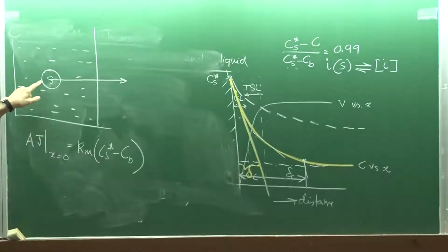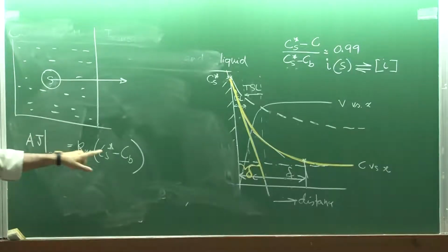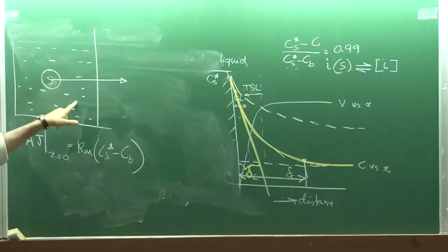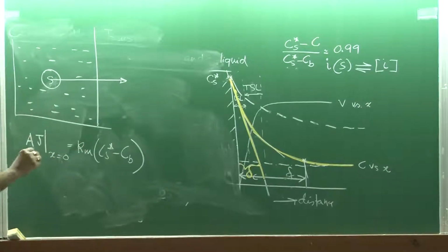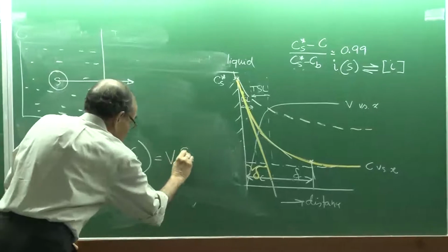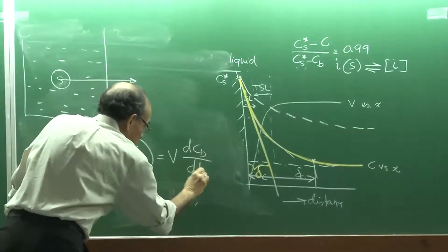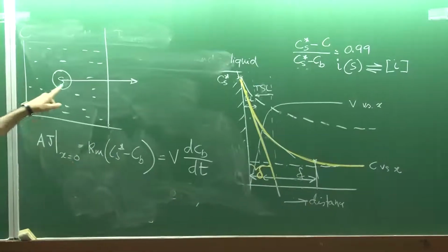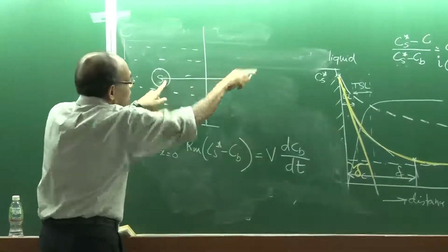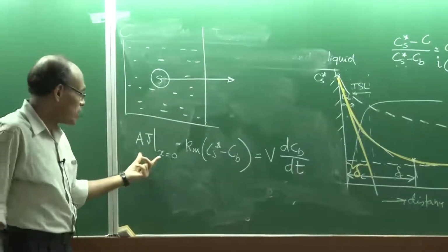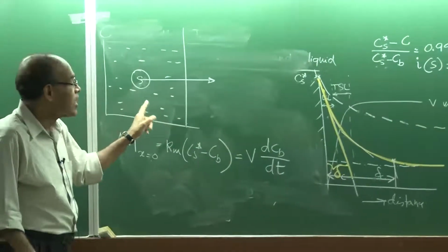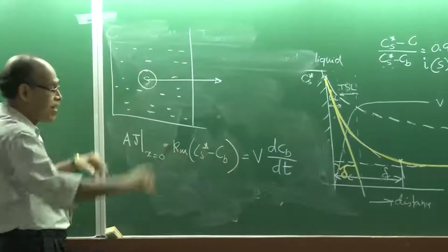Okay? Whatever is the material which is being lost by the solid is exactly equal to the material which is gained by the liquid, because this represents a closed system. There is nothing coming in, nothing going out. So this term essentially represents the rate at which material from the solid is going into the fluid in terms of kg per second, and this essentially represents the amount of material gained by the fluid, and they have to be equal because the material cannot escape.